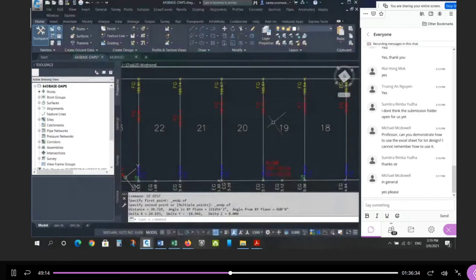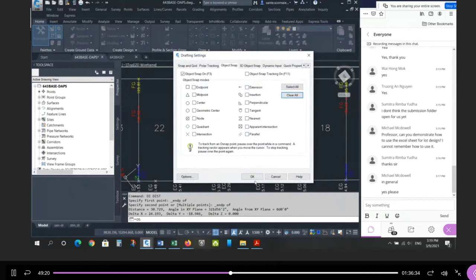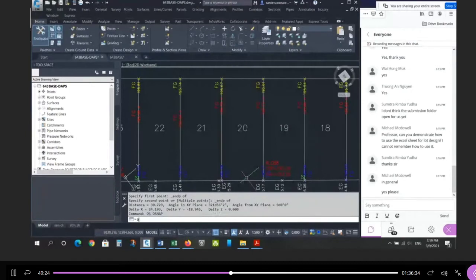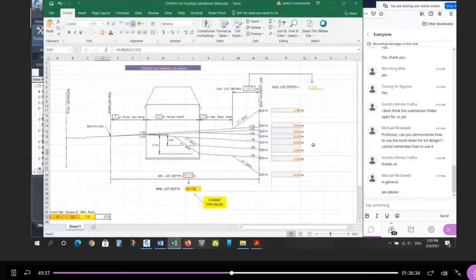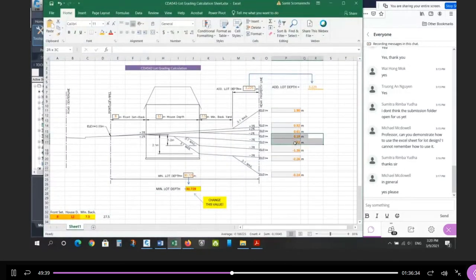All right. Now that I have that dimension, I'm going to measure the distance. I'm going to turn my OSNAPs to node, and measure the distance, DI for distance, from the front to the back. So I'm going to do 2120. I'm going to go here, and I know that it's -382. So now I go to the spreadsheet. -382 is between these two numbers, so there should be a solution where the front is 2% up and from the back 2 or 3.